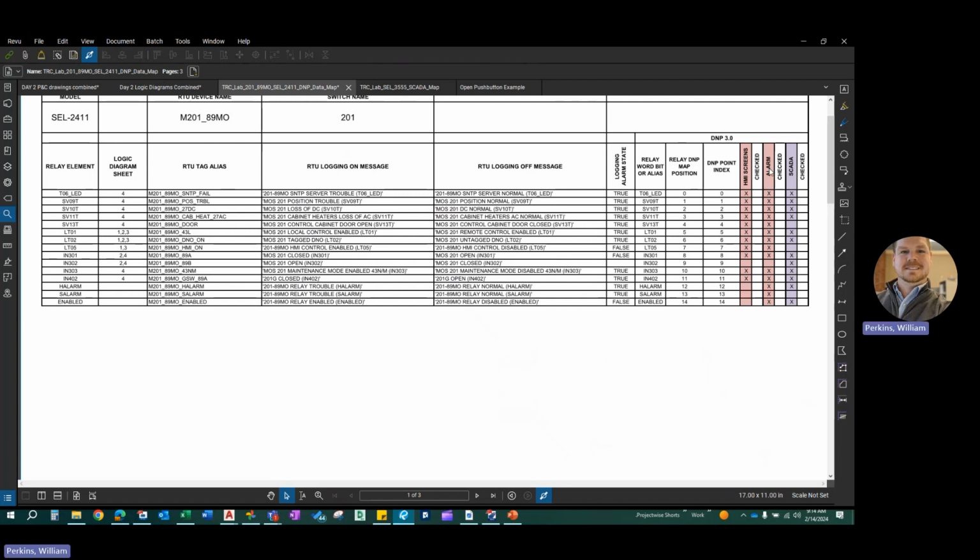The next column is the alarm. At the top portion of the HMI, there's an alarm section, and it's only text. There's no visuals, there's no animation. It just shows your active alarms. So within that alarm section, we're going to want to bring all of these points in whenever they alarm.